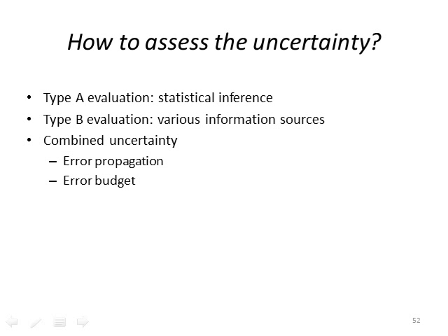We assess the uncertainty of this system. In general, there are two ways that we can take. Type A evaluation, statistical inference. Every component in the system, we will run statistical tests, input and output tests, to look at the random variable, how the output is going to vary with the input over all conditions that our system will see. So each component that we have, the pressure sensor, the beaker collection of the raindrops, our analog to digital conversion system, our display, etc., all of those individual components or systems have to be evaluated for all of the noise that the systems will see, statistical inference.